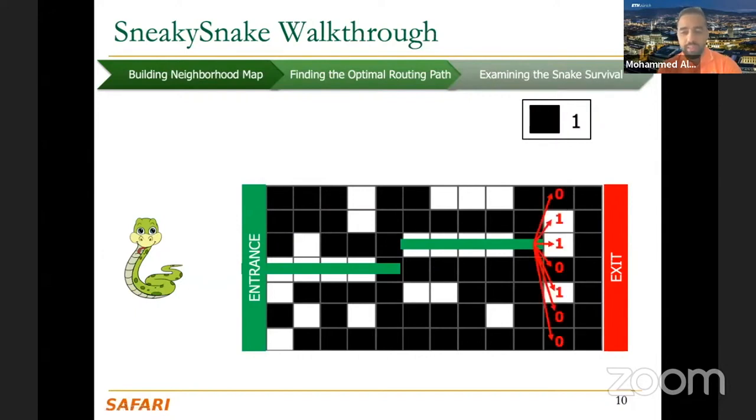Now we keep calculating each row. And in this case, you can see that we find 3 paths with the exact same number of available steps. So all of them have a single step to move forward. Which one do we choose? As I said, this is a tie, and to break the tie, we need to choose any one of them. It doesn't really matter. Now, some of you could say, how come it doesn't matter? Because if I choose one far from this path, I'm going to use a vertical path as well, and that is a cost for the silicon or for the metal layer in the VLSI chip, right?